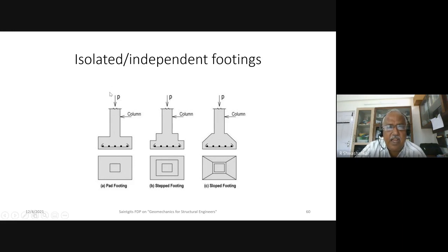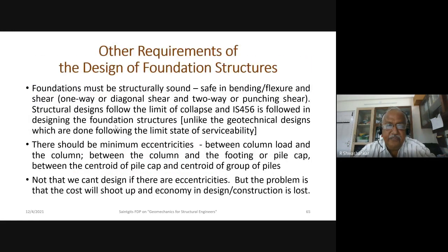The structural analysis provides this load P and any other moment. So I just design this footing, assuming this footing is the only one that is there. But this footing is not independent. It has so many other footings. Even if one footing fails, there will be a readjustment of loads, a redistribution of loads. So that's why soil structure interaction is very appropriate.